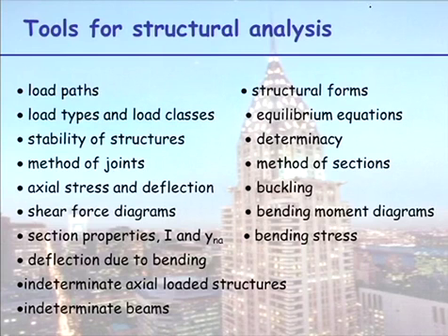So we started off with load paths. Okay, we now know we need to follow the way loads work through a structure. A common question I'm getting now with Project 3 is, Lizzie, do I put the roof loading on the secondary beam? And I'm saying to you, you work through the load path, you tell me whether the roof load is acting on the secondary beam. So this is not a high-tech question, this is a logical, let me follow the loads through to the support. If the load is not passing through that part of the structure, it should not be loading that part of the structure.